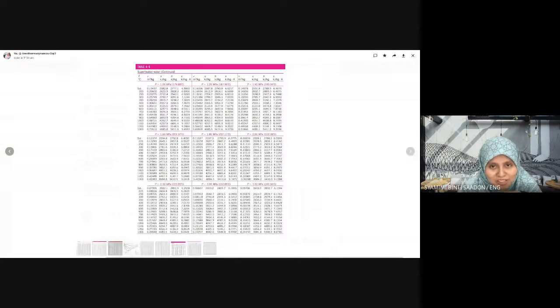Okay, let me switch slides. So this one, 2 megapascal, 400 degrees Celsius. The saturated temperature is lower, so it's along the saturated vapor line and above it. So at 400 degrees Celsius, the enthalpy is 3248.4. Two megapascal, 400 degrees Celsius, superheated water.